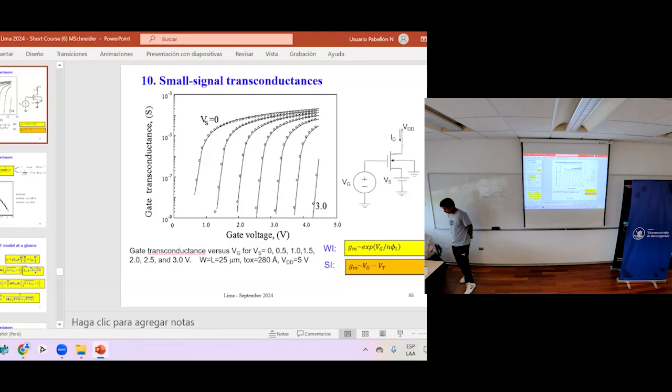Say this transistor, let's say that a given characteristic depends on the number of dopant atoms. But here you have 49 atoms. You have some variation, 51 here, 50 here, and 48 here. Now, you see that the characteristic depends on the number of atoms.